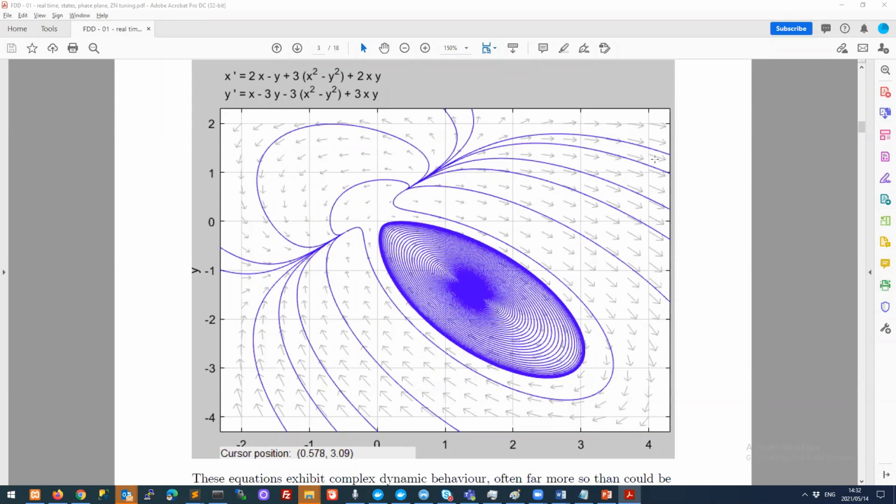And now when we look at this map, we can see that there are some interesting features here. You can see, number one, that there's a point here, which is what we call a repulsor. So you see that when you start near this point, the system tends to run away from this point. Can you see that from this point, all the trajectories lead away from it? So this is a point, in a sense, that the system doesn't like. The system tends to push you away from this point. So you start out at this temperature and concentration, the system is definitely going to push you away from there.